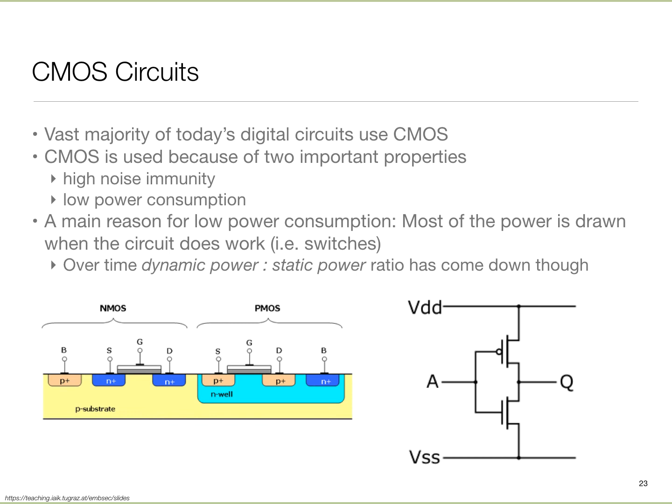Okay, so fundamentally, the property that these circuits have is that if nothing is happening, no new input is coming in, and inputs are stable, let's say we have stopped the clock, they consume, other than that leaking power, really no power. It's only when we have activity, that is, bits are changing, that they consume power, because of that tiny amount of time when they're changing state and power flows.